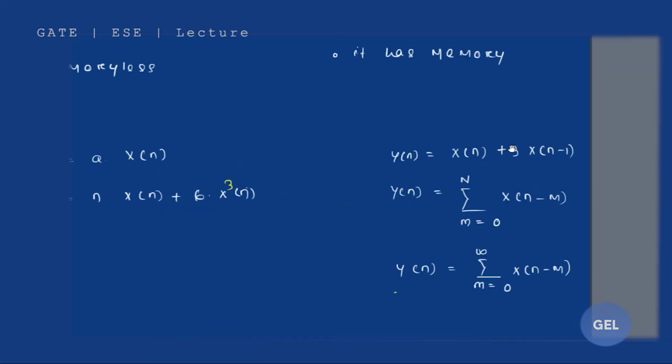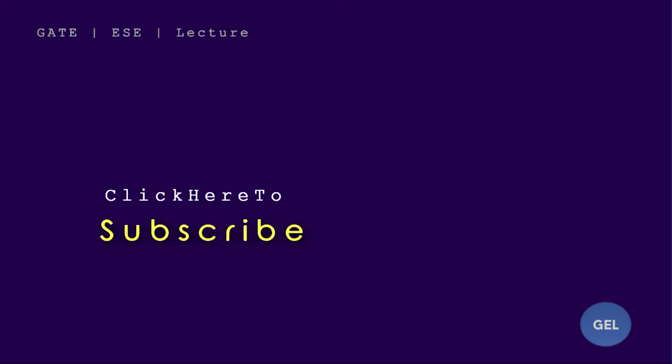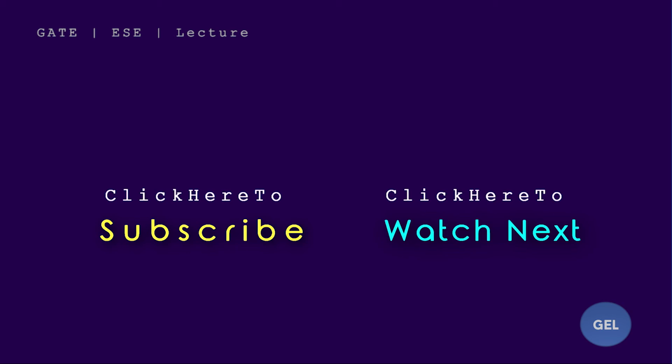That is, it is depending on the present as well as past input. So this is dynamic. It is depending on a lot of past inputs. It depends on a lot of past inputs and future inputs. So these three of them are dynamic discrete time systems, but two of them have finite memory, listen to this, finite memory, and one is a dynamic system which has infinite memory. Clear? These two are dynamic systems having finite memory, and this is a discrete time system having infinite memory. Now moving on to the time variant and time invariant case, it is the same principle that we have discussed in our continuous time domain, that is